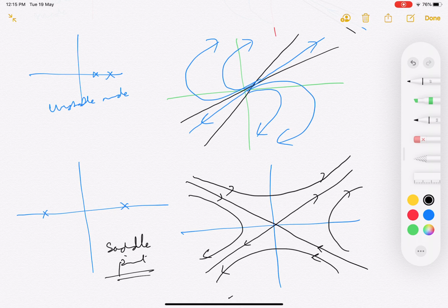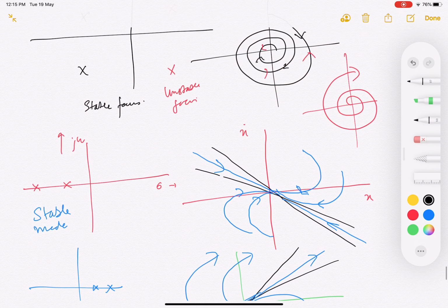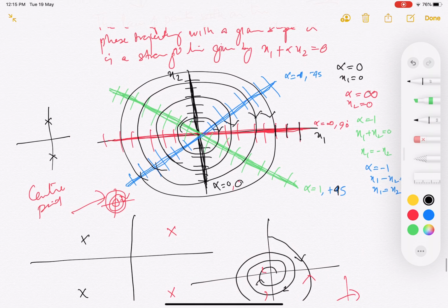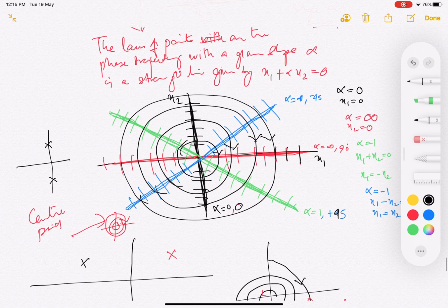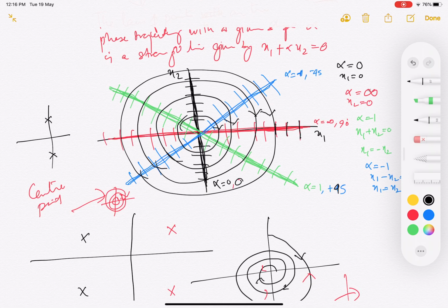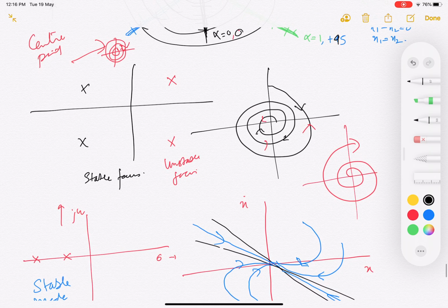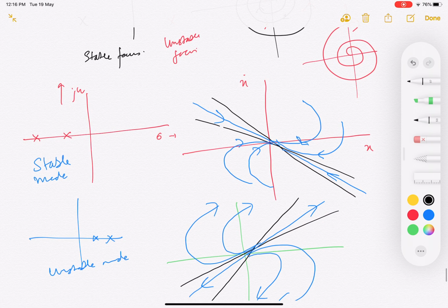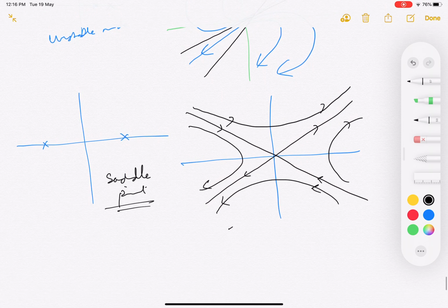To summarize, we have drawn the phase portrait for a linear system, the system that we already saw. We have also seen that we can draw this phase portrait analytically, and there are two methods of doing it. Graphically, we can do this by drawing isoclines, and we saw that we can get a circle for the system which was marginally stable. And if we do this for systems which have different kinds of pole locations, we get typical phase portraits given by these formations here.